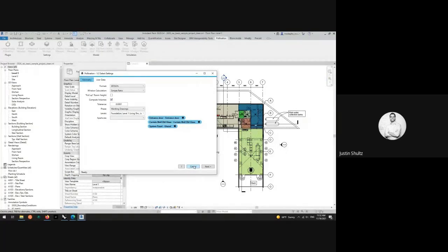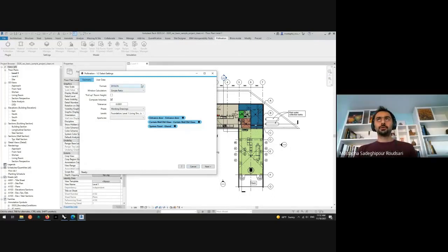Quick question: when should we use HBJSON versus DFJSON? Well, if your model is fully extruded and you don't want to fix the rooms inside Revit, then that's when you can use DFJSON. If you have the time to fix things inside Revit and the model is something you want to reuse over and over, it's better to talk to the model owner and use this room manager to fix things inside Revit, so you can use HBJSON. That will decrease the time for post-processing inside Rhino or other software that you use for simulation.